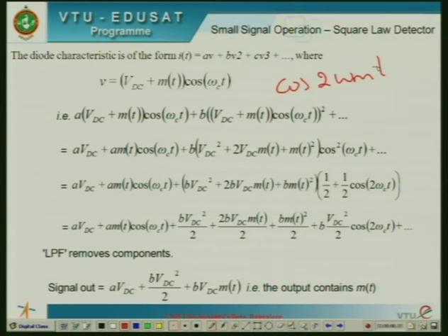The modulating signal will be translated by a frequency of 2. So this component is not required for us. Even if it doesn't have a carrier signal along with it, because we are squaring the signal, the frequency of the modulating signal m(t) is translated by 2. So we don't need this component.